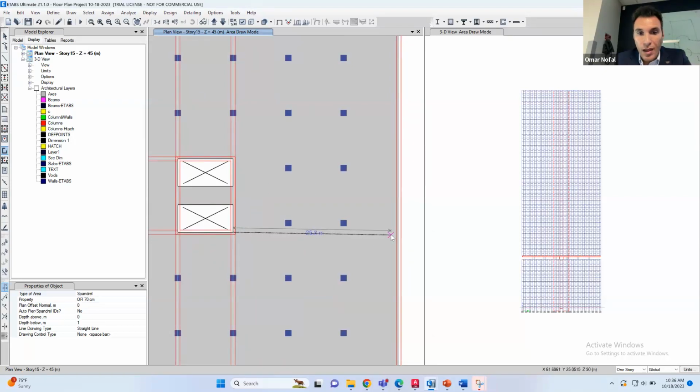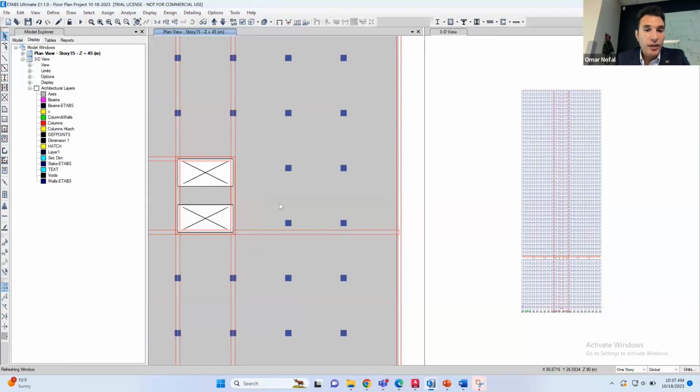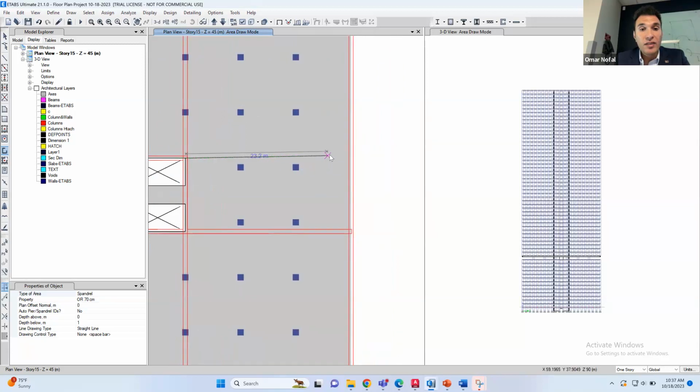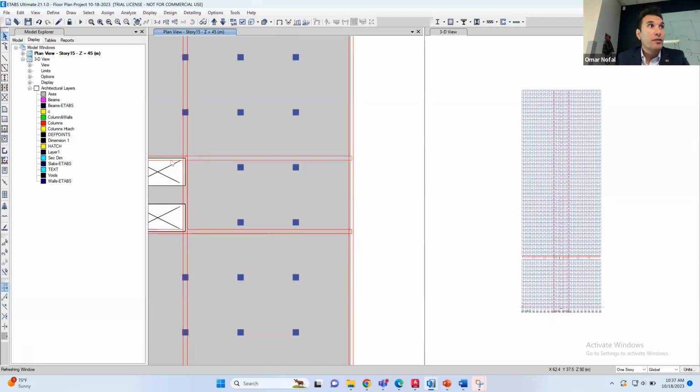So I was saying that if you can connect these columns with the outrigger, if you can keep them on this line, that will be much better. But usually the farther the columns, the better for the moment. If these columns are in the center of the outrigger, they are useless because at that point the stresses are zero.